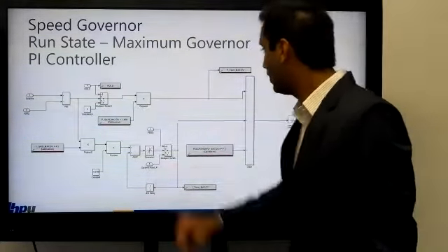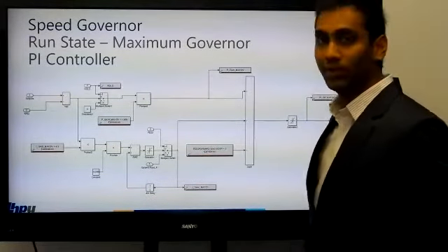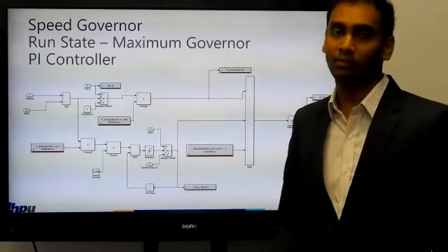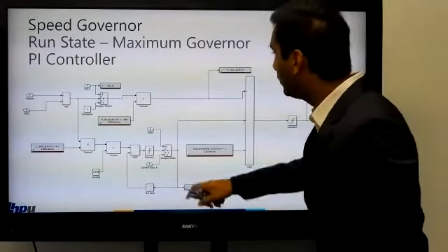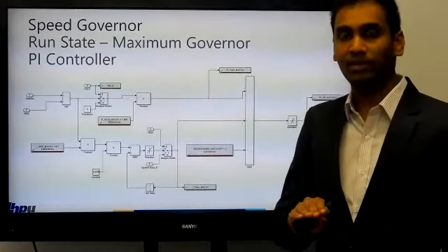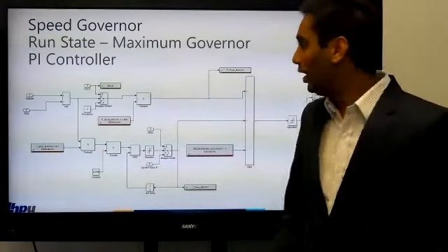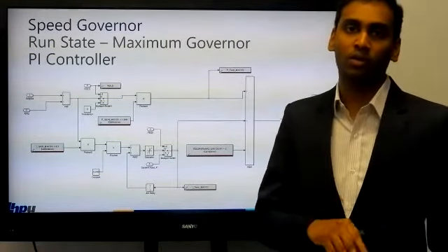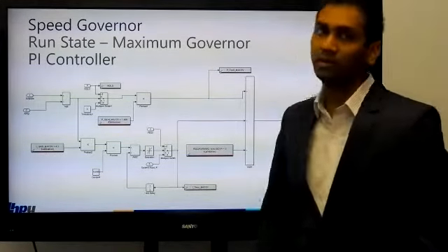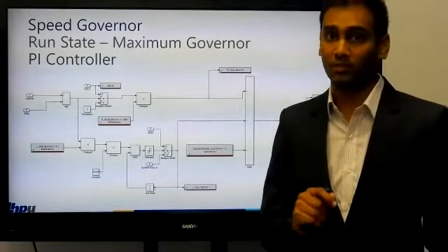One is the hold state here, and one is the reset state with a dynamic input for the item. So as we talked about before, when the engine reaches the maximum governor state, which is above 1500, your P-term goes to hold and it doesn't provide any fuel when your accelerator pedal is less than what the min of fuel is. And then if your accelerator pedal is more than what min of thinks it is, it will start activating both the P and I terms, and it will start removing fuel from the engine to maintain that 1700 RPM of the maximum speed.